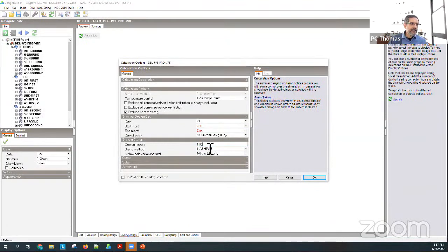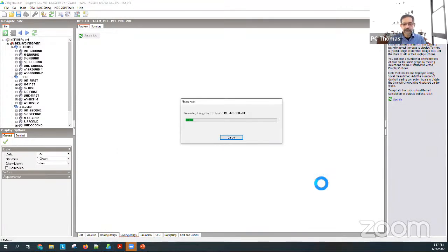Now, I'm not going to put any oversizing. I'm going to ask for the correct sizing, so my design margin is 1, okay? I'm using the ASHRAE heat balance equations to do the calculations, and the airflow is going to be based on the sensible load only, because that's generally how mechanical engineers size the airflow, okay? And that's why I said you may need some theory to back up the air conditioning design that we're showing you. So if I hit OK, it will go away.